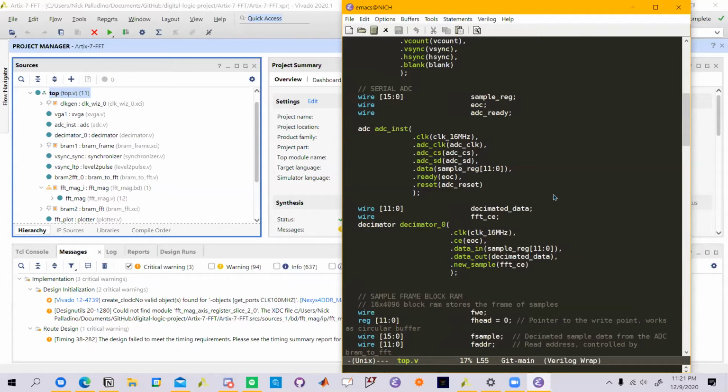And this is basically just a way of downsampling in the actual hardware. So rather than sampling at a slower rate from the microphone, we are throwing out every 32 or 64 or however many samples we want to, and that will reduce the overall bandwidth of the actual FFT output. So if we sampled at 1 megahertz, that would not give us much resolution in the audio range, but by downsampling with the decimator, we're able to cover a majority and a little bit past the audio range, which is around 0 to 22 kilohertz.